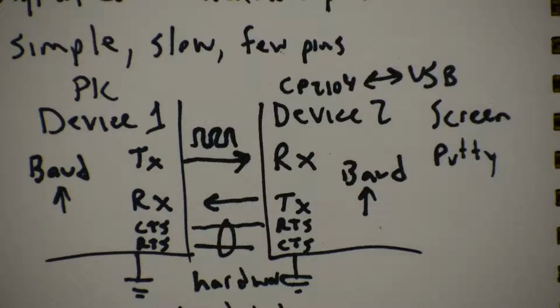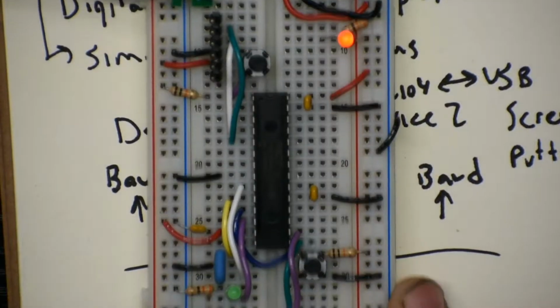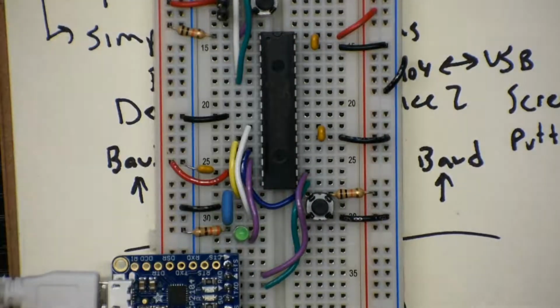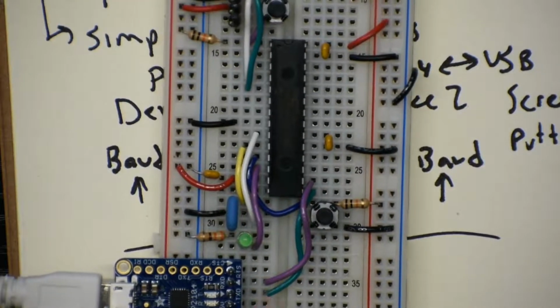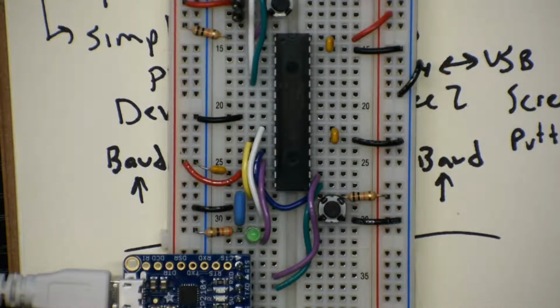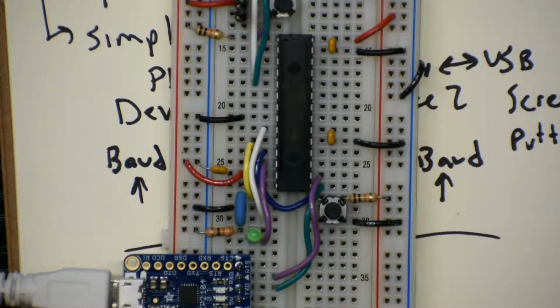So why don't we take a look at the PIC for a moment. And I'm going to talk about a few things here so that we can do some bookkeeping. One is that this PIC has 28 pins, but not all of them are I/O pins. So for example, some of the pins are for power and ground and things like that. So we have very limited numbers of pins here, and the end project in this course is going to involve using all of the pins. And actually, it's going to use more than all of the pins. So we need to get some pins back.